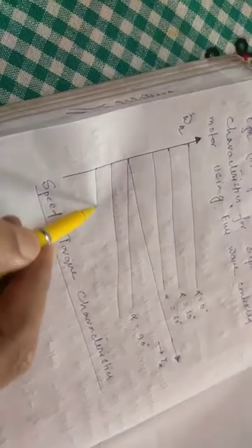With further increase in alpha beyond 90 degrees, that is from 90 to 180 degrees, the plots will continue like this. That is, the plots will be parallel to each other, but the point at which each cuts the speed axis will change. So this is basically the motoring region. There is a motoring region for alpha from 0 to 90 degrees. That is the first quadrant operation.